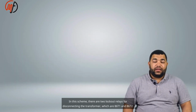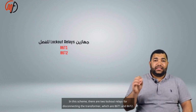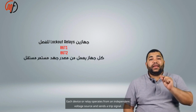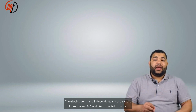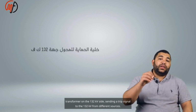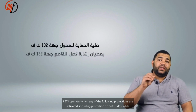In this scheme, there are two lockout relays for disconnecting the transformer, which are 86T1 and 86T2. Each device or relay operates from an independent voltage source and sends a trip signal. The tripping coil is also independent, and usually the lockout relays 86T1 and 86T2 are installed on the transformer on the 132 kV side, sending a trip signal to the 132 kV breaker from different sources.